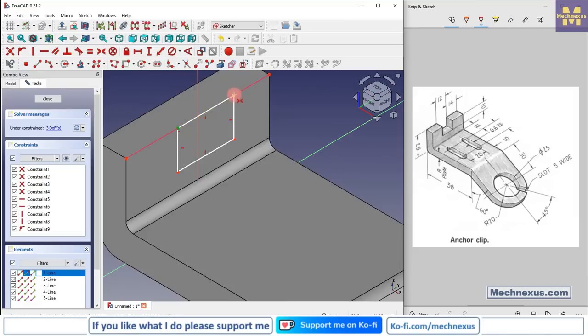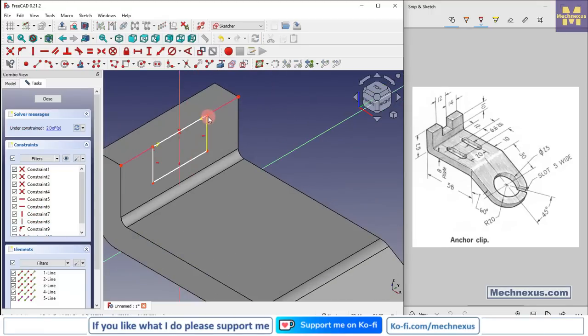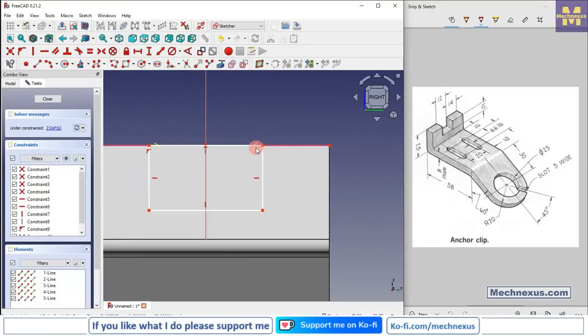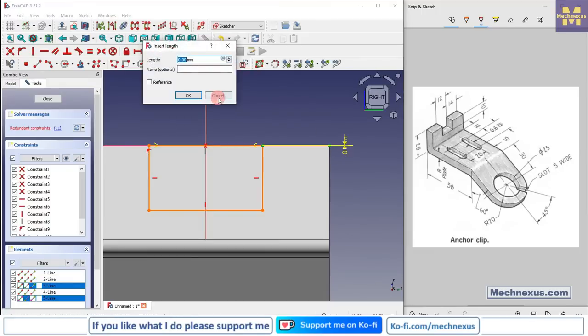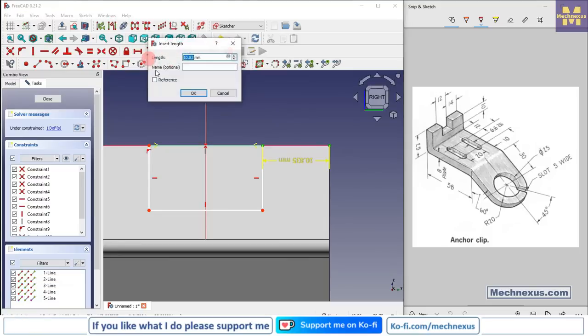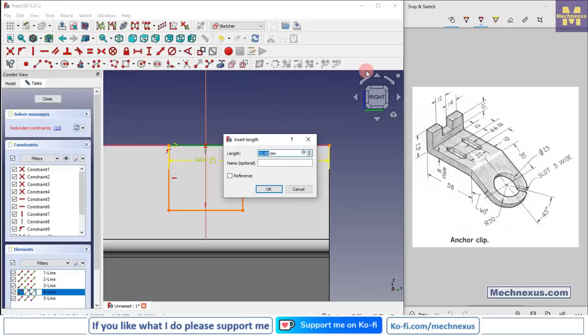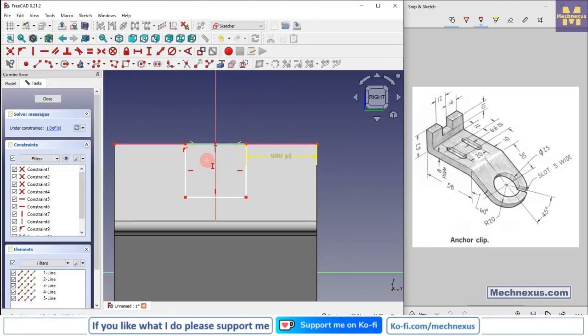Select this point and this point, and deactivate the conflict constraint, and we will switch to the right view. Select this point and this point, and add the dimension of 14 mm, and select this line and add the dimension of 12, which is already there,